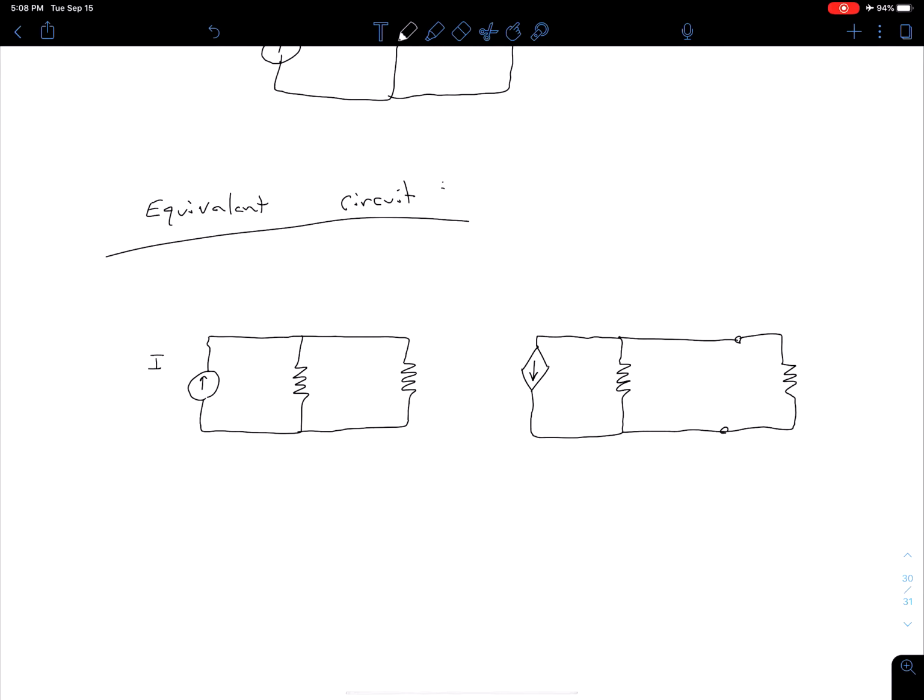So this would be our input current. This would be our source resistance, R_S. And let's go ahead and label this as our input resistance of the amplifier configuration, R_if. And so if we're not neglecting our source resistance, R_S, then this current, of course, is going to be different from our input current. So we can call this I_i primed, our input current primed.